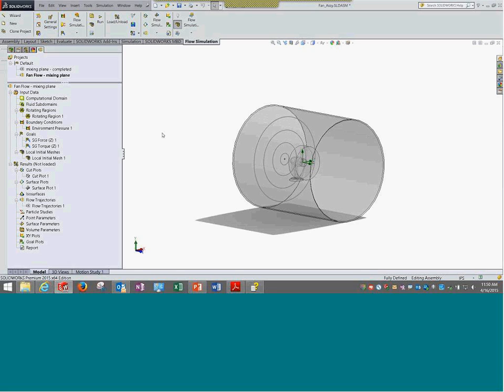It is the same flow as what is happening practically, but a few things may not be captured accurately, and hence that is the lag between what can happen in the practical and deriving the fan curve using the software. So just be aware of that. When the discussion comes up with the customer, you can say yes, we can do it, but this is where we hit the limitations. If we are comfortable and aware of those limitations, then definitely FlowSimulation can be used to derive the fan curve.